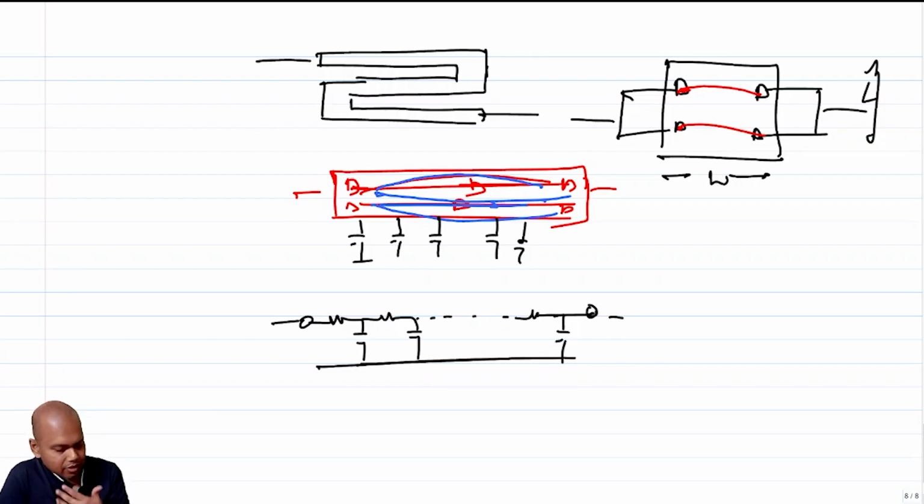So again, having said that, if this were a data converter course, then probably I would have spent a lot more time talking about how to match two resistors, what are the things that you need to take care of in order to ensure that two resistors are almost as identical as possible. But fortunately, in RF circuits, we are much more concerned about capacitors and inductors than resistors. Resistors sometimes appear when we do not want them to, right? So most of the course goes in mitigating those effects, right?